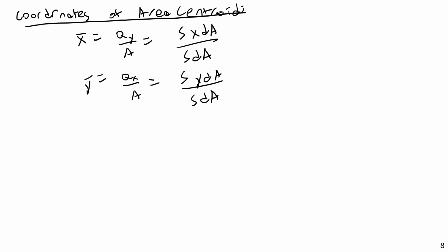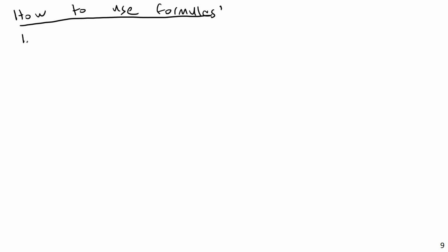So how do you use these formulas? Well, in this particular lecture, lecture 14, we are primarily concerned with solving for centroids directly by integration. So we're dealing with shapes that are relatively simple and that we can directly integrate. So, how to use these formulas. One, construct a differential element.